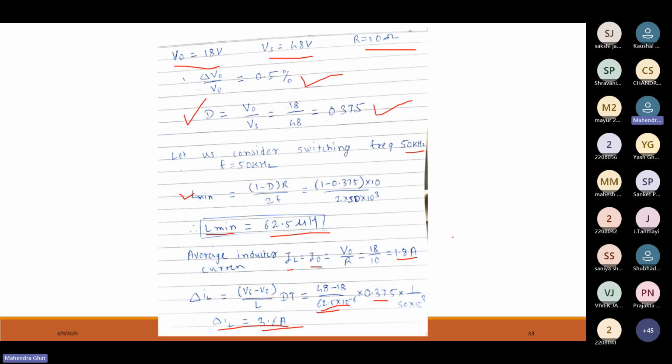One more aspect is that if you go for higher and higher switching frequency, there is a phenomenon called EMI/EMC, electromagnetic conduction and electromagnetic emission. So filters are required for any converter, and the requirement of this filter again increases as the switching frequency increases.